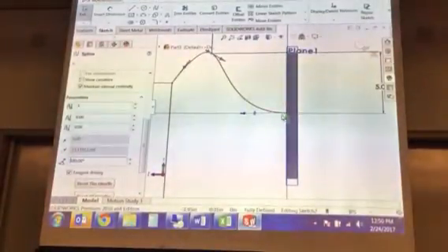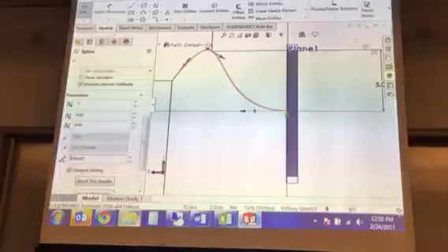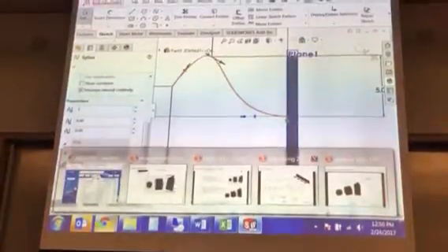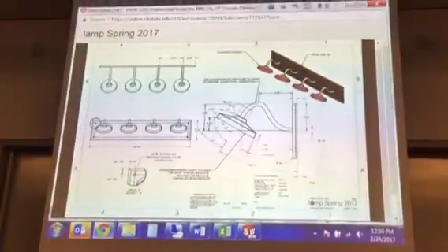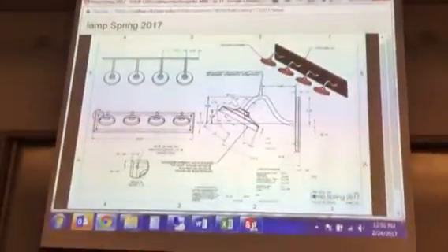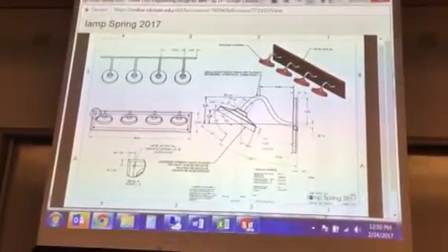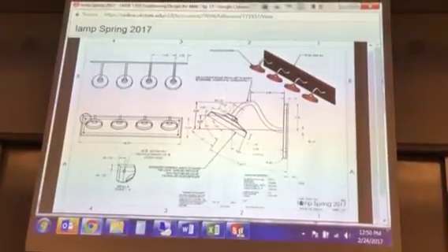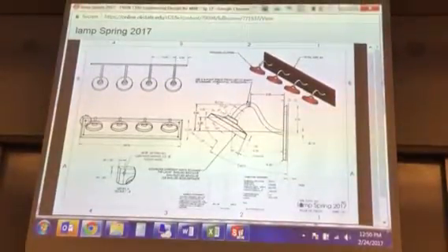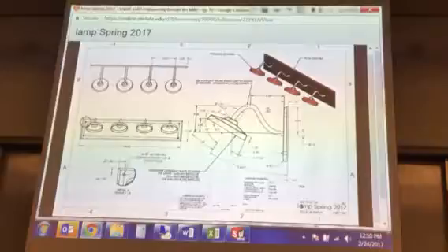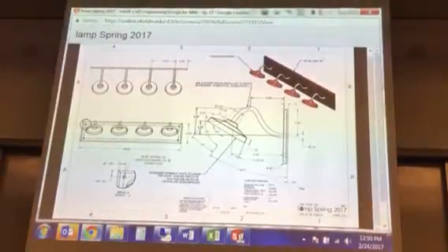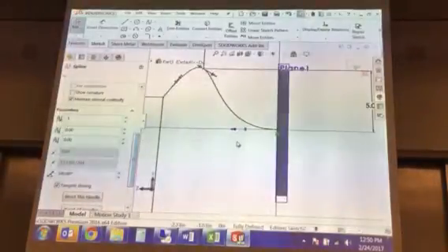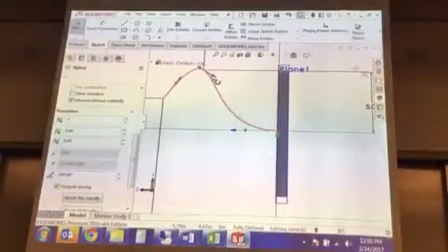Okay, so now I've got on the drawing, and how you know how to do this is on the drawing, it says it's a 3-point spline from left to right, so 1, 2, 3, and it's 30 degrees off of vertical here is the angle, horizontal, horizontal, so that means flat here and flat here. So this one here, we're going to do the same thing.